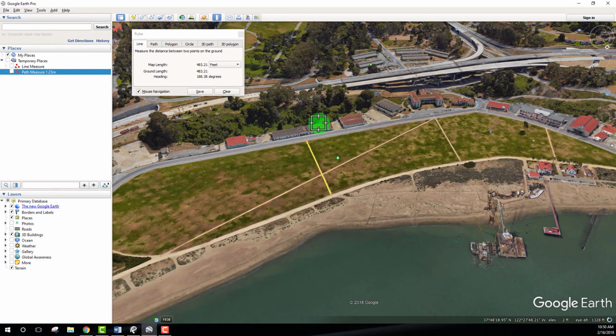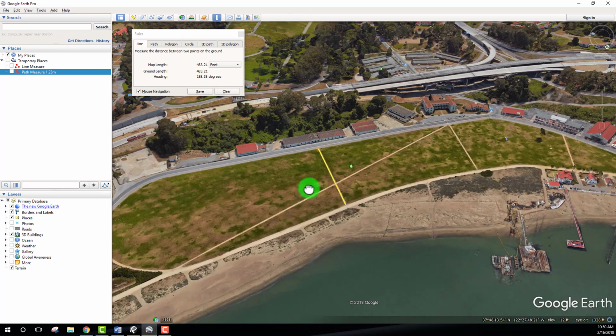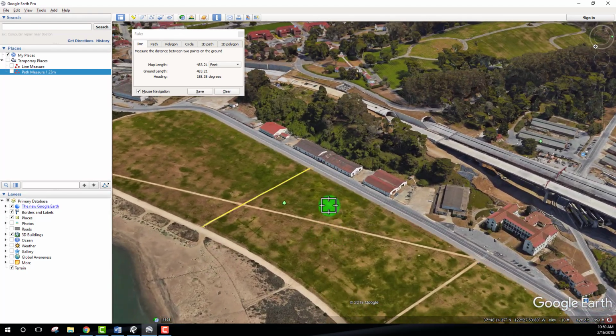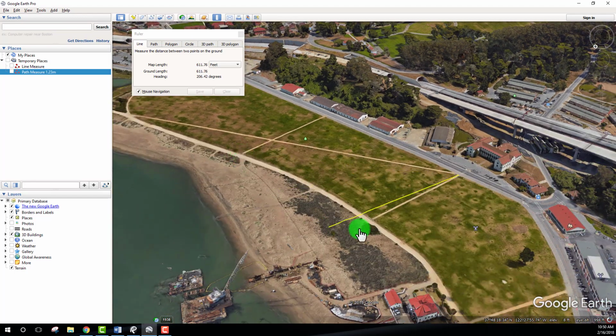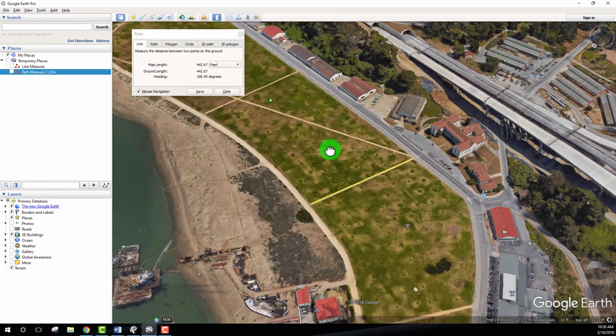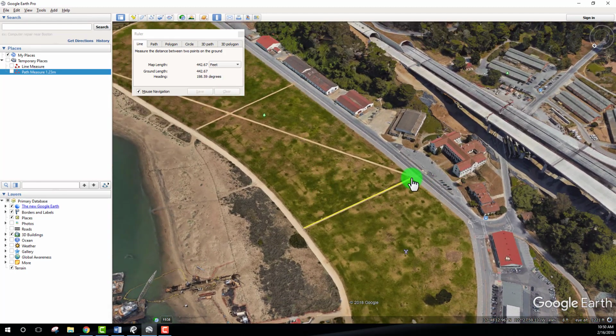But if you're not using a 3D mouse, then you just want to make sure you have your mouse navigation turned on so that at any point you can take your view, rotate it around, zoom in, grab these nodes, pan, grab the other node, and move it around and do all that while you're in the input method. So we don't have to finish any of these before we modify it. We can do that right on the fly with this mouse navigation turned on.